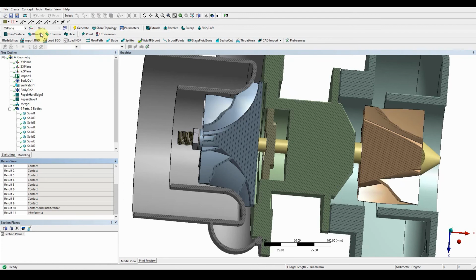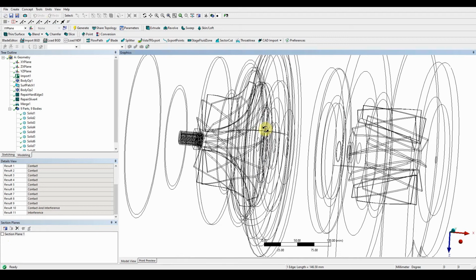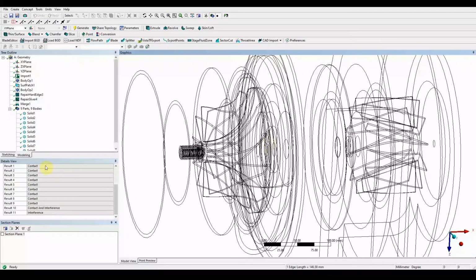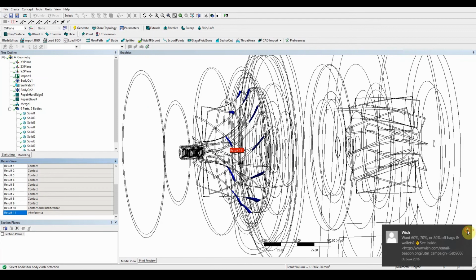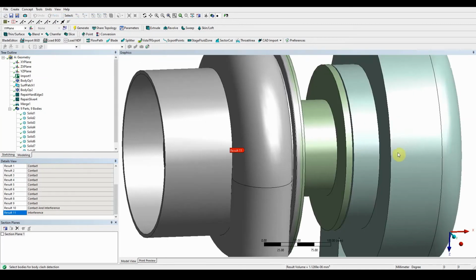And again, if you get rid of this and go to view wireframe and look at the various geometry intersections, you can see where it's all being connected, and it's got some intersection problems. Okay, so moving the compressor casing may solve the problem, and what we want to do is have a look at that. So we look at the overlap. So compressor, so both in a shaded view. So view, shaded view, exterior.